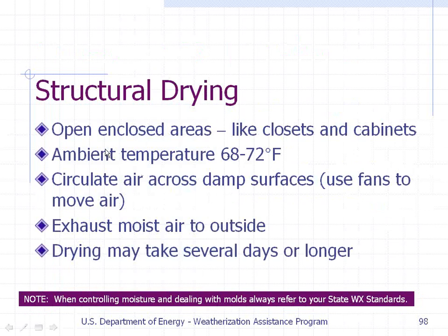And structural drying. You need to open enclosed areas like closets and cabinets. Maintain ambient air temperatures inside between 68 and 72 degrees. Circulate air across damp surfaces by using fans to move air. Exhaust moist air to the outside. Now, drying may take several days or longer.